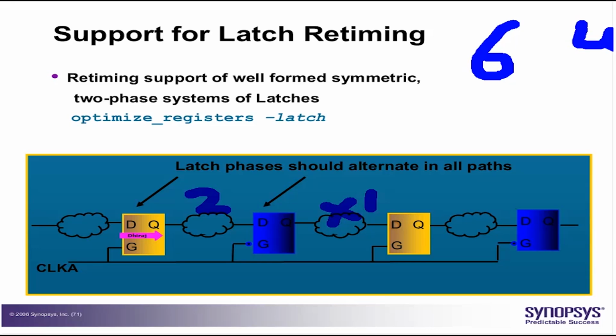Assuming the latch delay in the transparent phase is close to negligible, the data at this point arrives after the delay of cloud 1 and cloud 2. So in effect, the latch here is transparent, and we say it was able to borrow timing from 2 to 1 or from 1 to 2 as the case may be.